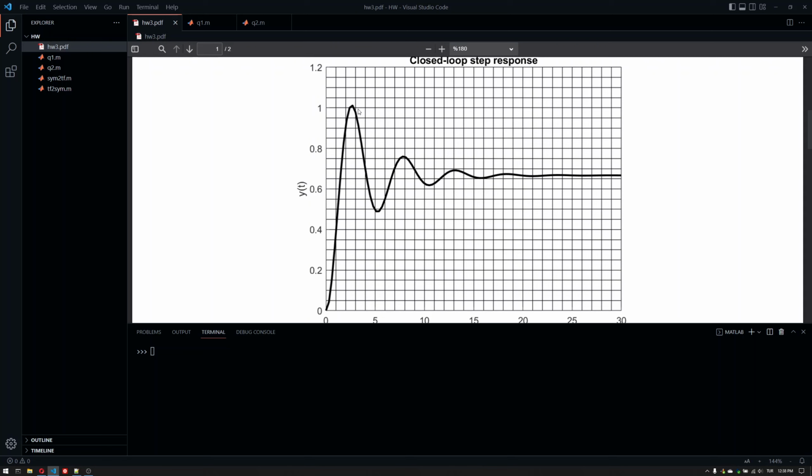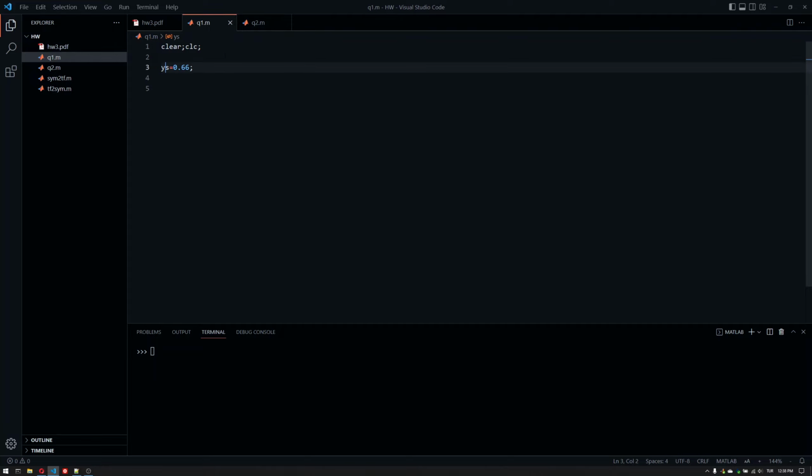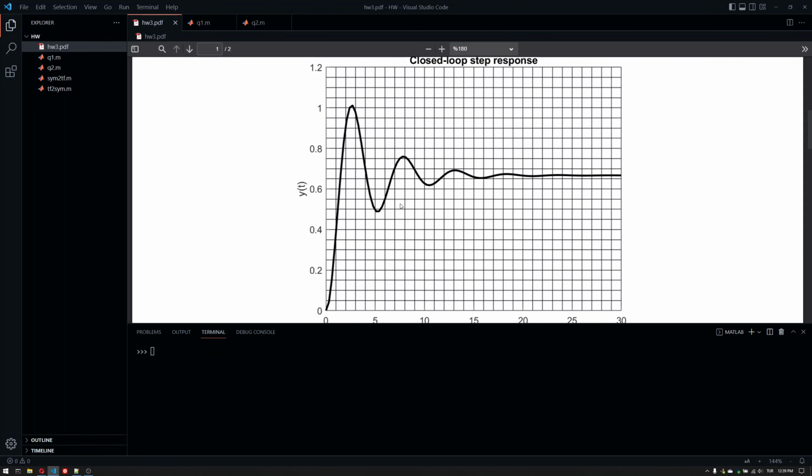The other one here is basically the peak value, because when I have the steady state value and the peak value, I can calculate the overshoot, and that can give me zeta, for example. Here I'm going to take the peak value as 1 because it is slightly more than that, but you can take whatever you want. I'm going to take the peak value exactly equal to 1 because I need to refine it anyway, so that wouldn't be a big deal.